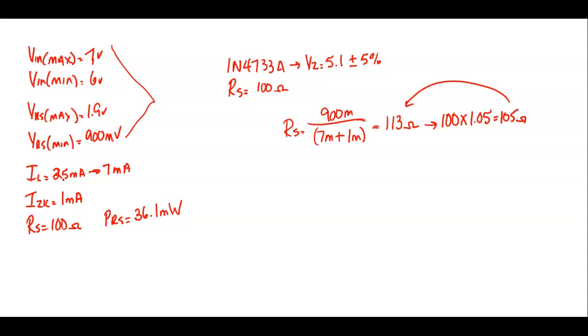So then we're going to hook up our circuit. We're going to use our 100 ohm resistor, which I got to go find one. And then our Zener is going to be in there like that because it's a positive supply, right? Everybody okay? Okay. And then we're going to have to vary the current.